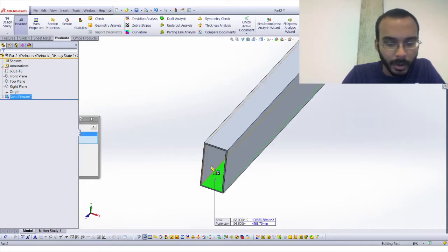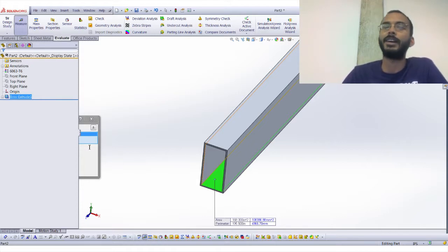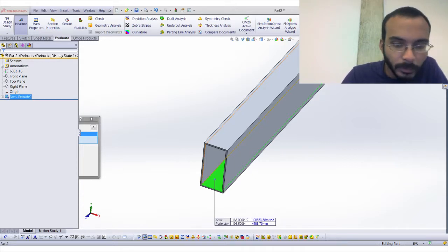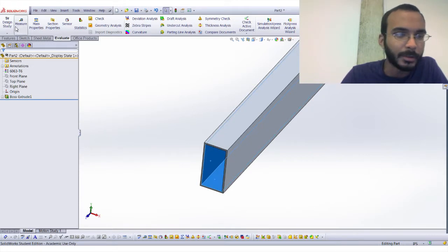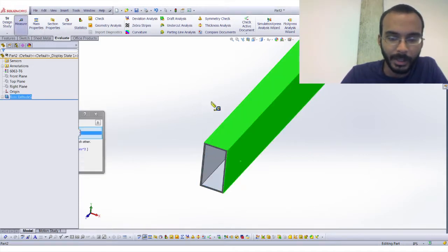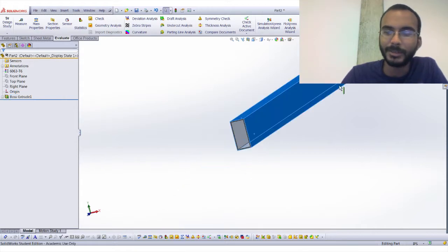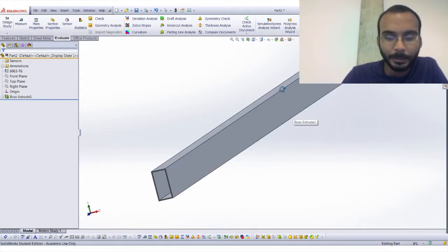But you can also check things like, are things perpendicular? So it'll say those 2 items are perpendicular to each other, which can be really useful, because often you might have something that looks perpendicular or looks parallel, but then it's actually not, and then when you go to make it, it would be really bad. So being able to check with the measure tool and actually seeing that, yes, this is truly perpendicular, is pretty useful. It'll give you things you don't need also, like total area of everything you select. If you want to know the full area of this part, it'll give it to you. Again, probably don't need that, but there may be a time when you do.